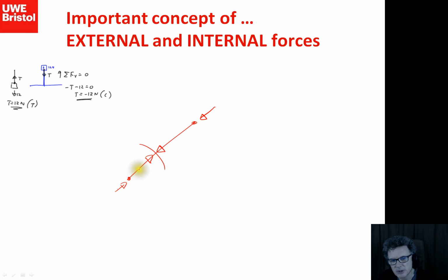The forces inside the member have to travel in the direction along the member only. That's the only way they can move, because where I take that cut, you can see that force is going to be moving perpendicular to those possible ways, the million ways I could take the cut through the member.